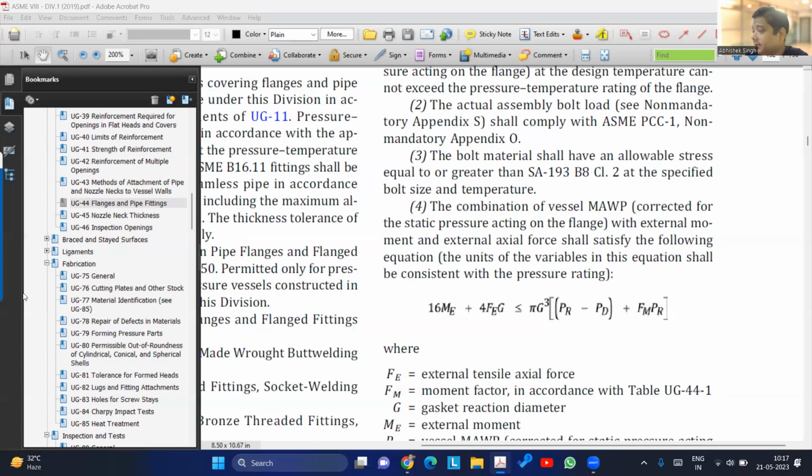Okay, first, the flange rating can be increased. That is one option. Now, if I don't want to increase the flange rating, then do we have any other option? FE analysis to qualify the loads? Sumit is saying FE analysis. We'll come back to that. Stiffener for flange? We're talking about flange derating, Amol. We don't provide stiffeners for flange. RF pad, increase thickness. What is the question? Okay, change the size.